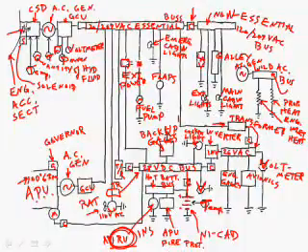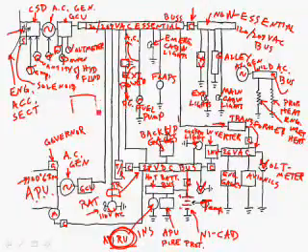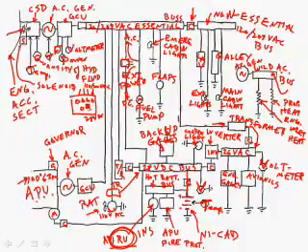External power may be able to provide high voltage AC, and it may be able to provide low voltage DC. It depends on the ground power cart you hook up to it. I've seen ground power carts with 3-phase AC, including the ground, and then another 2 for 28 volts DC and 120/208 volts AC. So it depends, but there are some carts that only provide 120 volts AC. I did it again, 120.